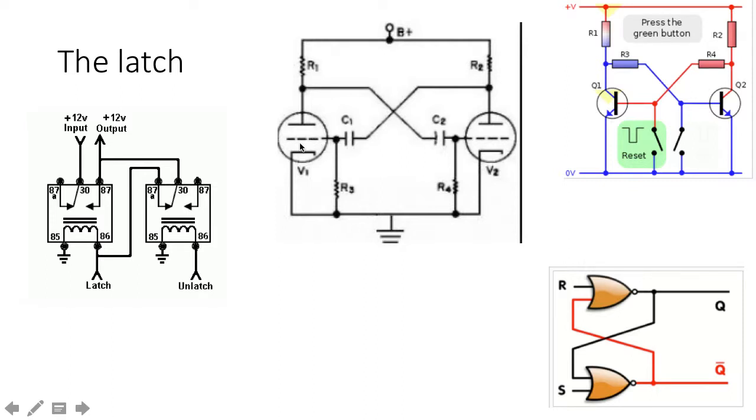This is what you call a triode. It has three elements: a cathode, a grid, and an anode. And the grid serves as a gate of power that goes from the cathode to the anode. When the cathode is replaced by simply a filament, and then you have nothing more than a filament and an anode, the filament can be used as what they call a hot cathode, and that's a Fleming valve, or a diode, which was originally used by Sir Ambrose Fleming when he was acting as a consultant for Samuel Morse to improve the sensitivity of the transatlantic telegraph.